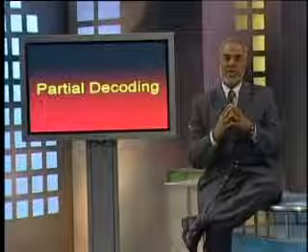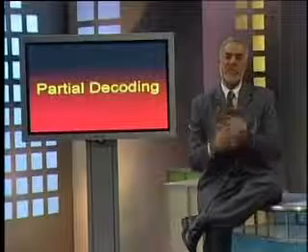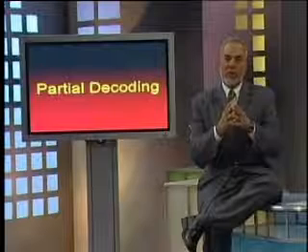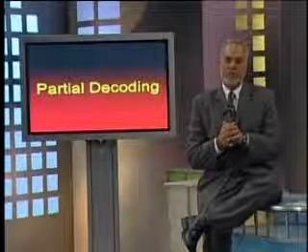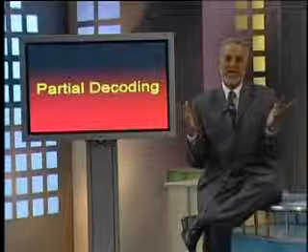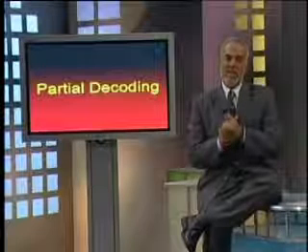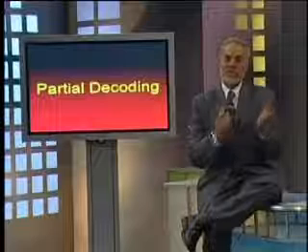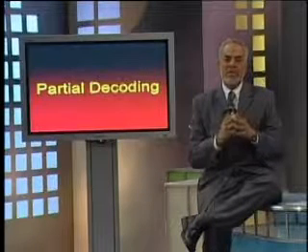The result would be that in this case, our total address space would be wrapped around, and this would be a wrapped around effect. For utilizing only 8 bits, the wrapping would be after 256. So it would be similar to modulo 256 effect in mathematics, which you know. So this would mean that if we have an address 00DE and another address 01DE, both would be mapped on the same actual address, right?